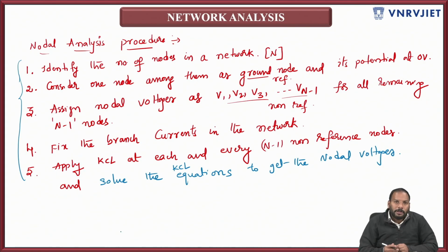Now we'll go ahead to solve the problem, but before that, every time along with KCL, we take the help of Ohm's law as well, to represent the branch currents in terms of nodal voltages.